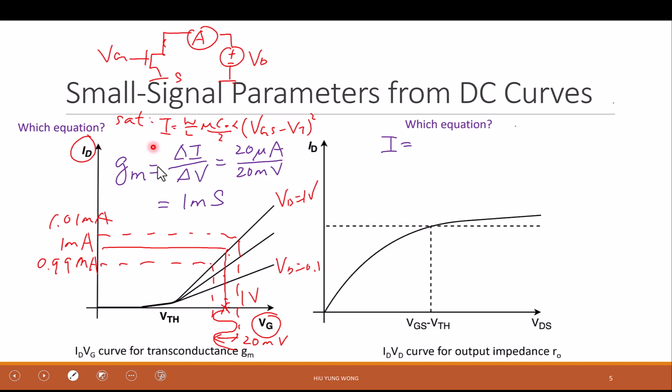We say, okay, I have this transistor. This is a nonlinear transistor. And the current depends on VG minus VT squared, which is difficult to solve. You see that it's so complicated, we even need to think about whether it's on or off. But once I know that it's biased at this point, I apply the signal, then I can just treat this as a constant slope, which I call the gm.